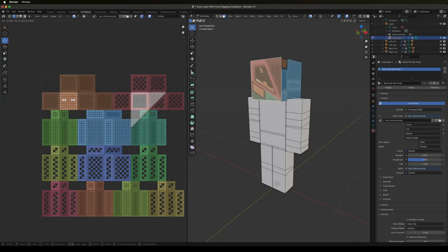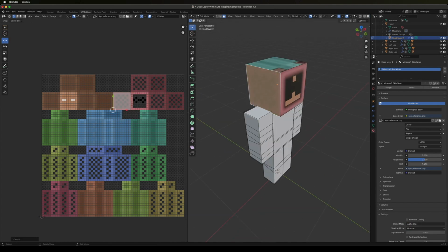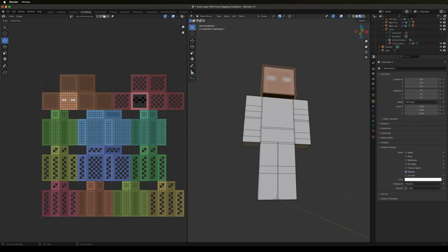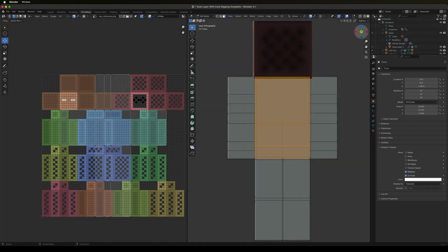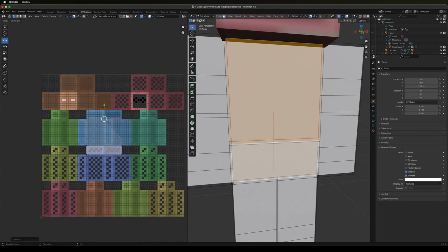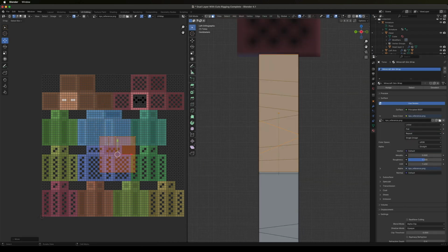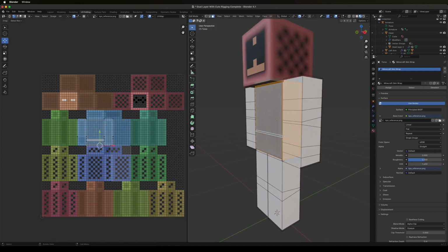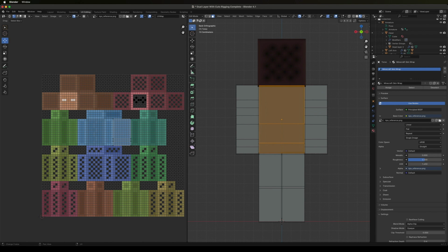Our next problem surfaces as we start to map textures to objects we've put loop cuts on. Unless we've been extraordinarily careful and lucky, our loops won't line up with easy to identify pixel boundaries, and so we'll get regions within the texture on the object where it appears squished or stretched. Unfortunately for the work we've done so far, the solution is to remove the loop cuts and reintroduce new ones that align with clearly defined pixel boundaries on the template.